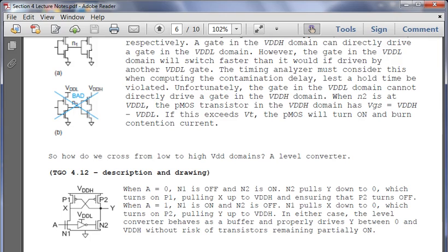And another thing for future designs, you have an instance where you've designed a domain to a higher level of voltage, and you design a second domain to a lower level of voltage, right? And they work fine. You put them together, they don't work, and you haven't properly thought about it.